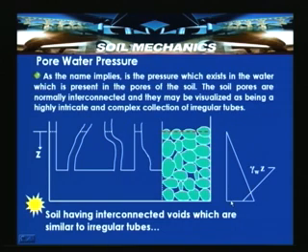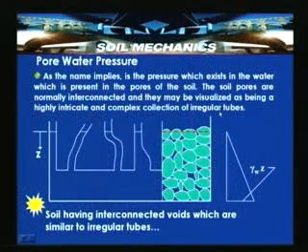The pore water pressure, as the name implies, is the pressure which exists in the water present in the pores of the soil. That is what we discussed in the previous slide. The soil pores are normally interconnected. We have seen that the soil pores are like a skeleton with interconnected voids, and they may be visualized as a highly intricate and complex collection of irregular tubes.